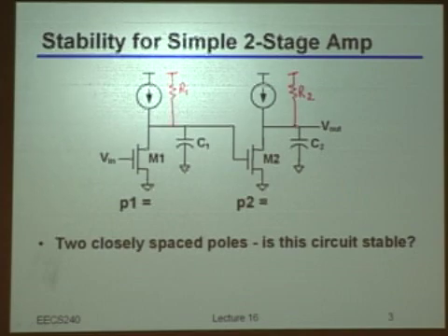If this is the situation, P1, most probably. Minus? Yeah, okay. It's minus 1 over R1C1. And similarly, the second pole will be placed at this frequency, or this omega, the generalized frequency, actually. So let's assume now that I've just placed these two poles really close-spaced, so basically at the same spot. Let's assume they are just piled one on top of the other.